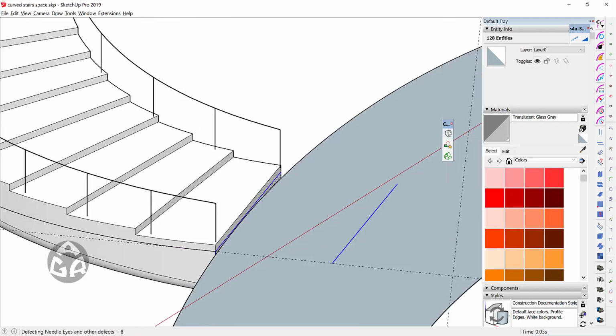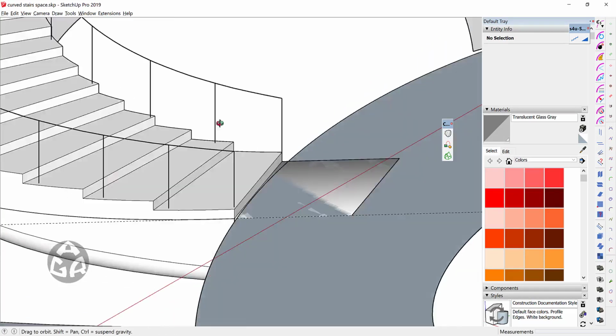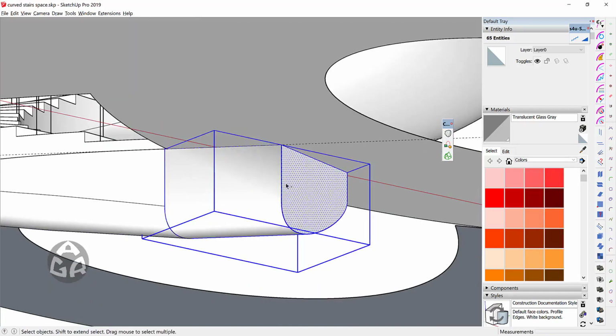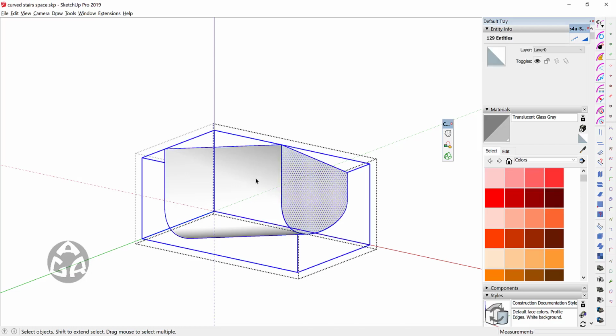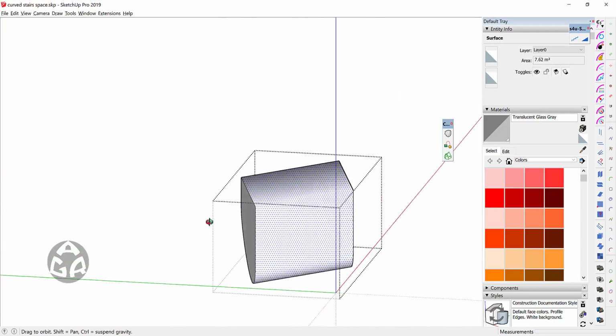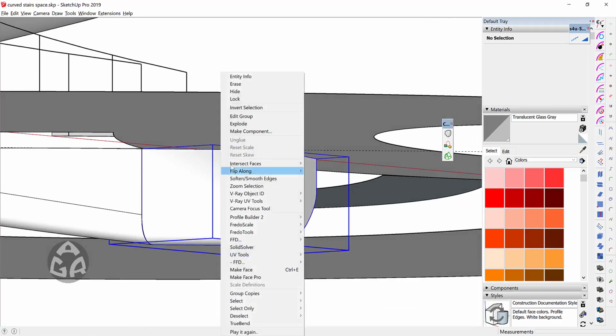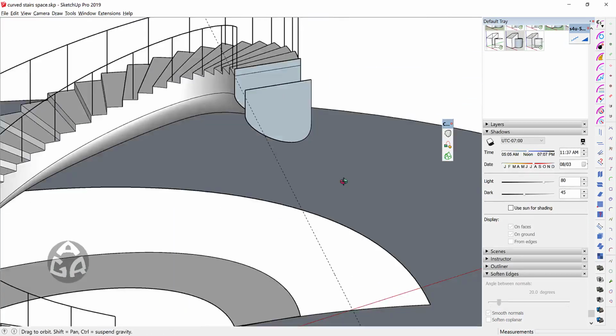and we will use the loft by Spline and click here once and click, and I will select the grouped surface or the created surface, the lofted surface, and these 2 end surfaces, and then group these all together and then go inside the group or edit group, and I press Ctrl A and then Ctrl Shift X for exploding this group, and then we will orient the faces and right click soften smooth edges, and also we will do so over here.